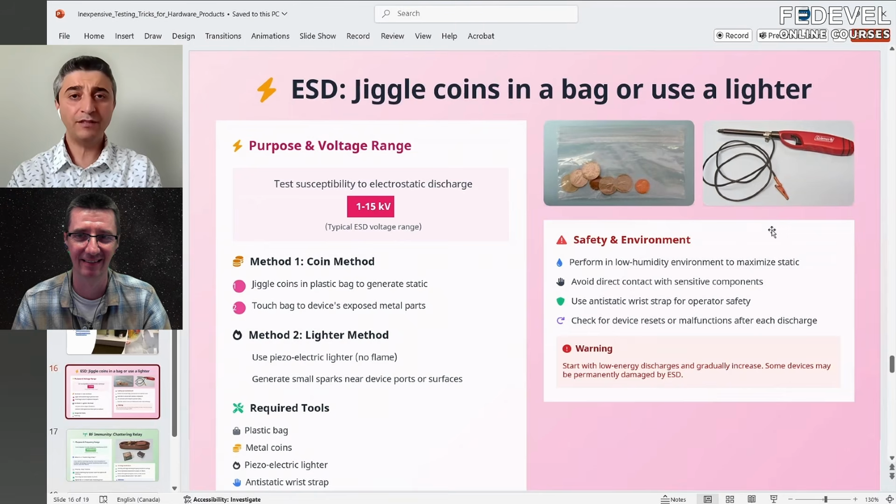Of course, if you have the budget to go for it, I advise you to do it. I have used this in the past, and it was very helpful. Like you mentioned, I had a design maybe 10 years ago. We were working on ESD, and there was a simple ferrite bead. The moment you have that ferrite bead, it basically fails the whole thing. You remove that ferrite bead and put a short, and it's gone. So definitely, and this is along the line of having gaps in your return path.